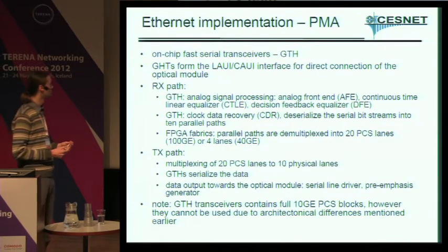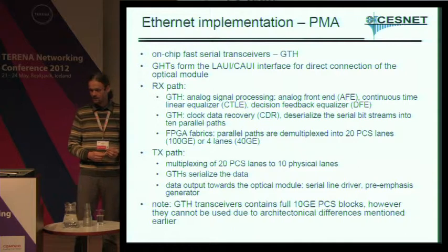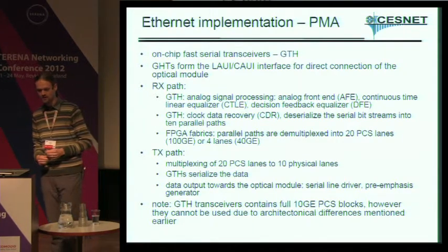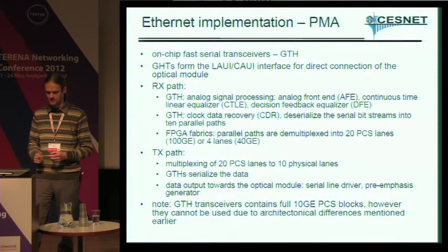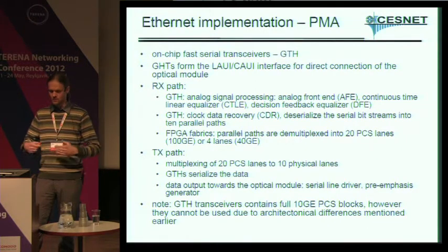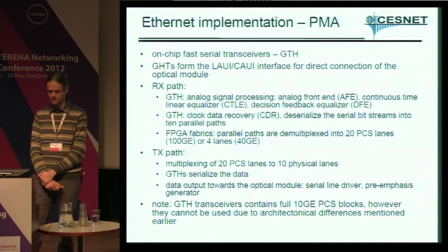The implementation of the PMA in the FPGA will use the GTH transceivers to create the interface to the optical module.